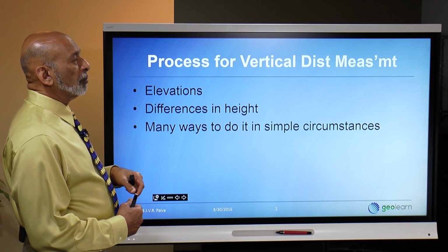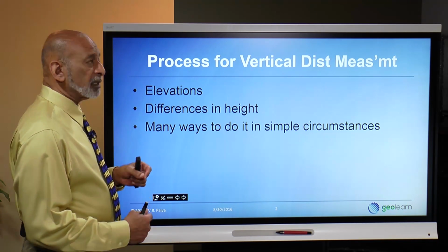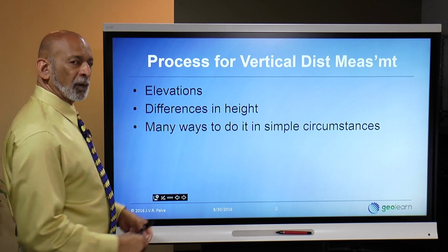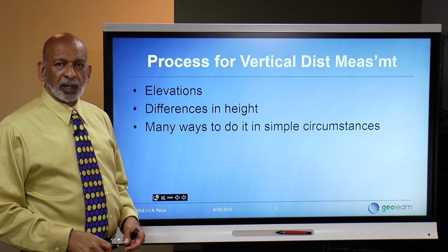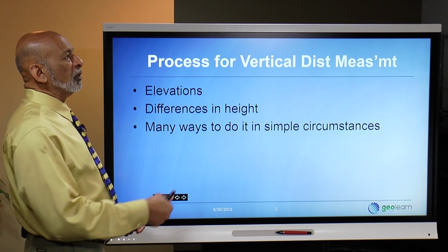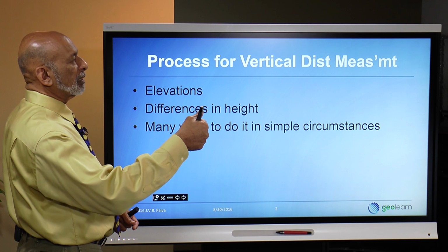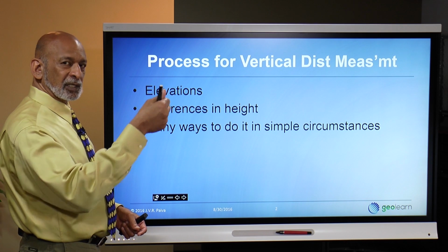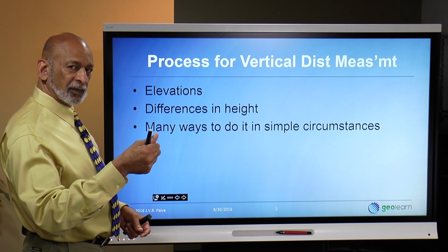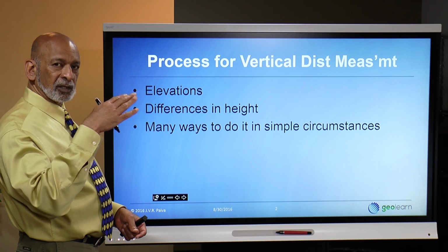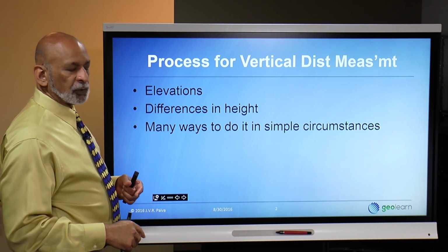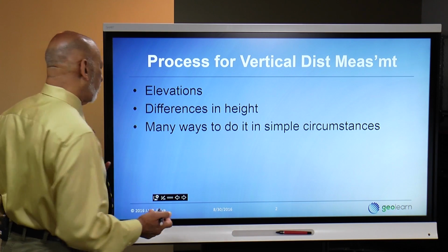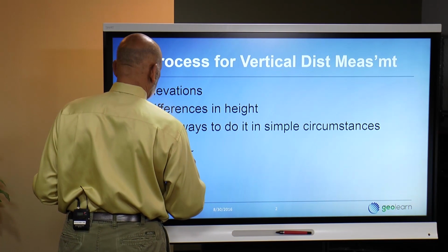You may have seen special measuring poles that are fiberglass, that are used to measure things like the height of a power line, because they need to move some equipment that's over height, perhaps down a road, and they'll use the measuring stick to figure out how high it really is to the underneath of the bridge, because the signs always have a little bit of factor of safety in them. They might measure to power lines and other overhead cables and so forth. These would all be what I refer to as direct measurement from one surface to another